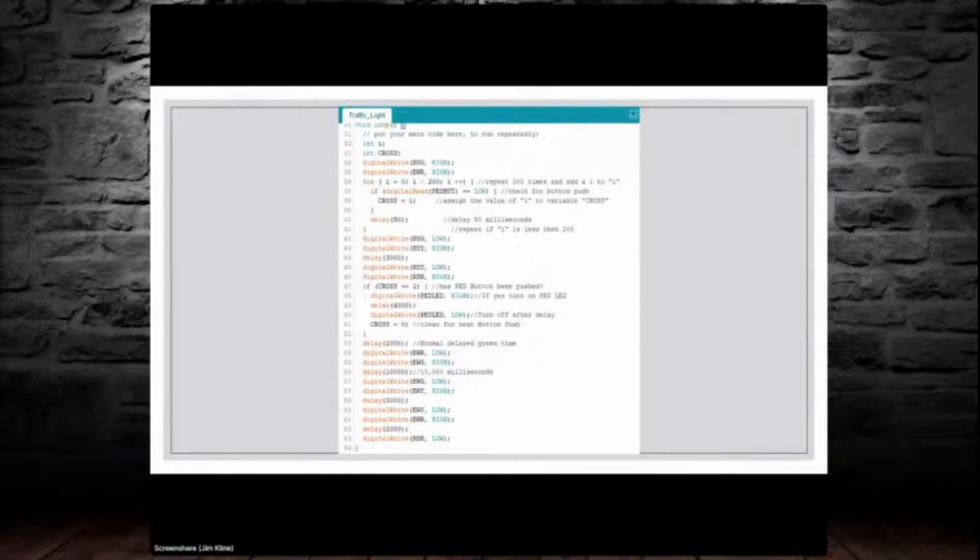So anyway, I'll leave it to you to complete the delay substitutions for the rest of the sketch. I didn't want to clutter up the code that you see here. I only put one instance of the delay for the button push, and then one instance of the actual area where you're going to execute and light the pedestrian light, and have the 4-second delay for the pedestrian to cross. Obviously, we have 3-second delays and another 10-second delay, etc., where this needs to be installed or substituted.